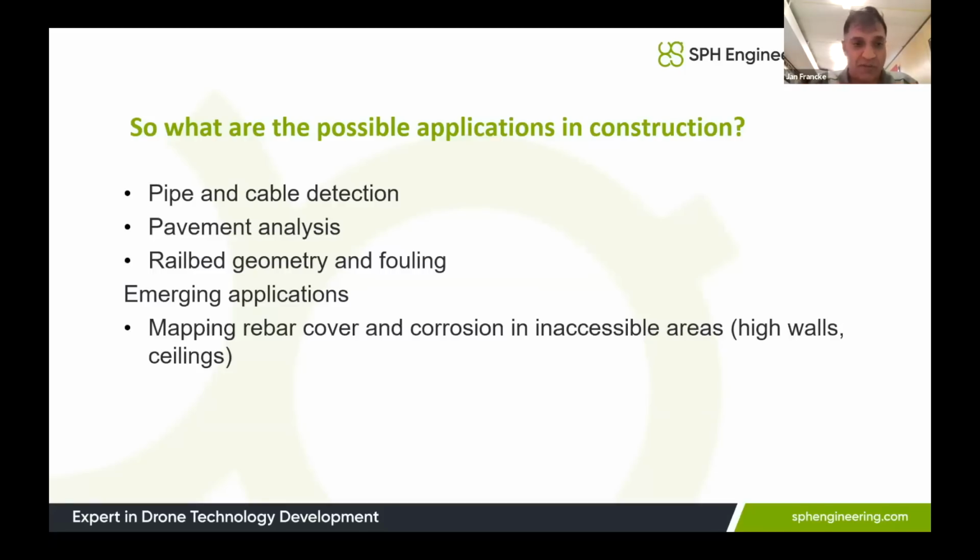Now, another one we want to talk about coming up is pavement analysis. What is that? Well, it's essentially using GPR, and this has been going on for 30 years, to map different layers of pavement, both in the pavement, the asphalt, and the subgrade beneath it.